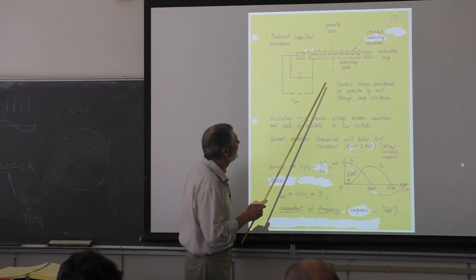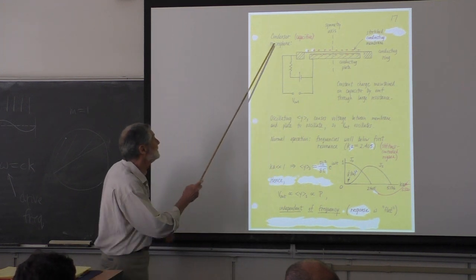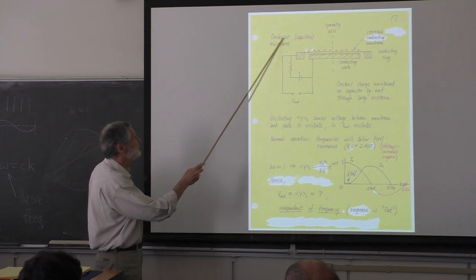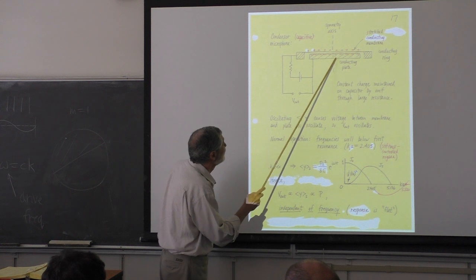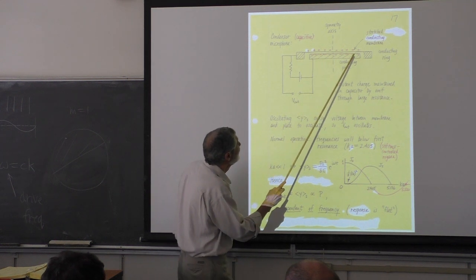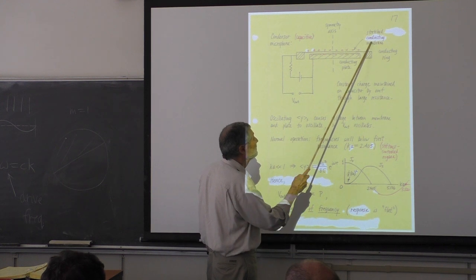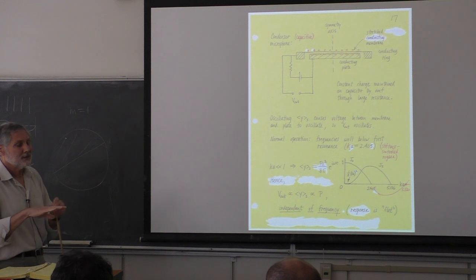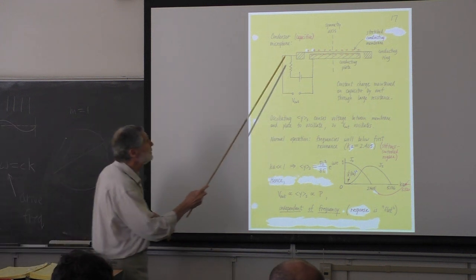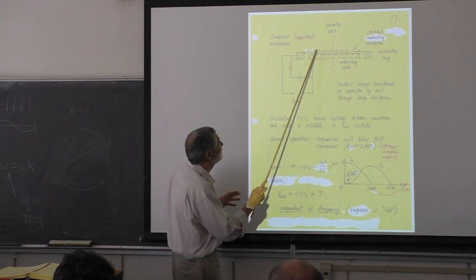So here's a standard capacitive type, or an older word people also use is condenser microphone. You see the capacitor here, there's two conductors. The membrane here is metallized. They've put a very thin layer of metal on there. Often you can see through the membrane, but that doesn't mean there's not a metal coating. There's got to be, okay?